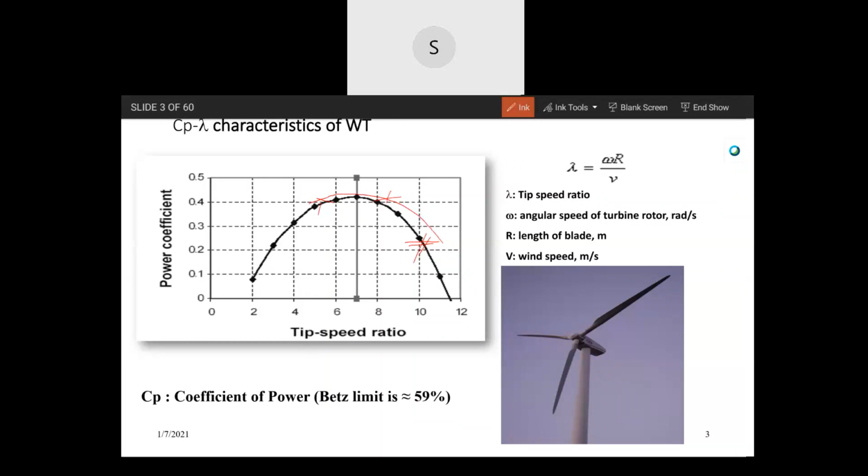When it works at a high wind, that is 25 meters per second, this efficiency will be much less, 12% only. We need to limit it because quite a large amount of power is contained at a large speed. All that power cannot be extracted. Maybe at a later stage, that part also we will be discussing. Anyway, understand that CP is continuously varying in the present state of the art machines, and the average CP will be around 20 to 28%.